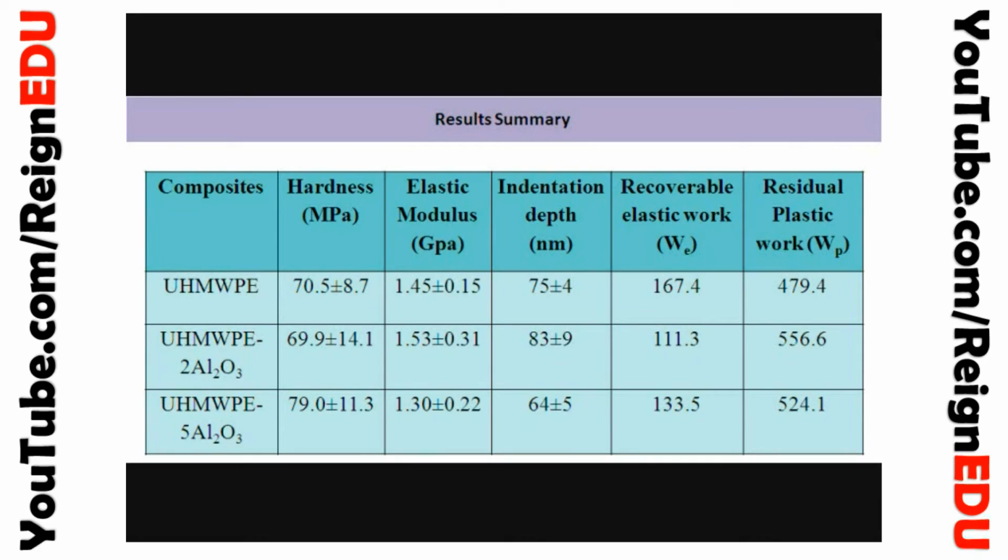These results show that ultra-high molecular weight polyethylene plus 5 weight % alumina composites show better mechanical properties than ultra-high molecular weight polyethylene, and also that ultra-high molecular weight polyethylene plus 2 weight % alumina composites are inferior to ultra-high molecular weight polyethylene alone. Also, addition of a larger amount of alumina increases the mechanical properties while a smaller amount does not.